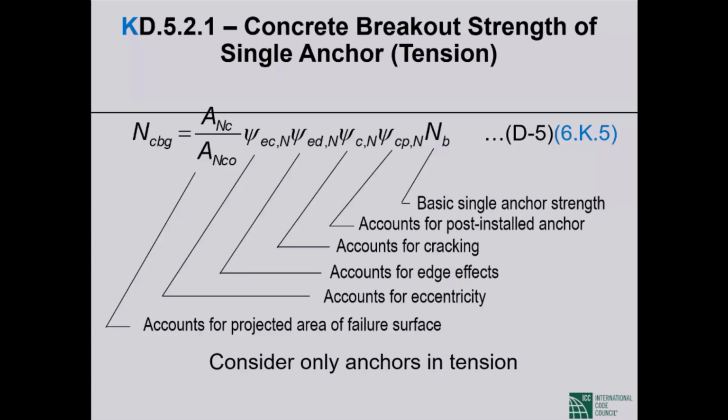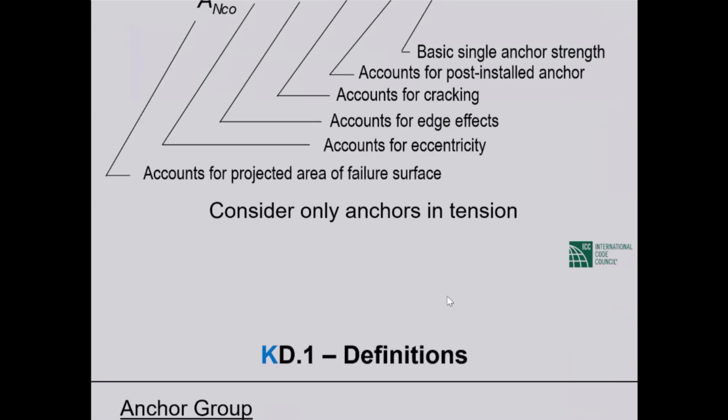Now, in addition to the correction factors you saw on the previous slide, there is an additional correction factor which is for eccentricity of load application. Psi sub EC, comma N, means it is for tension. So it accounts for eccentricity.